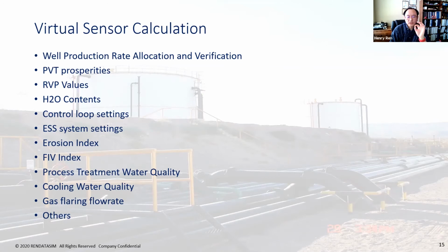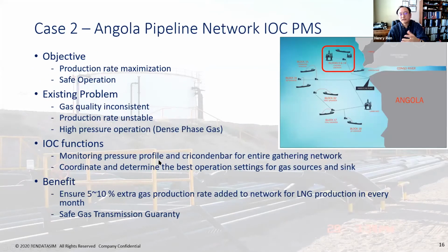And also for the key locations, particularly the downstream of the choke, each riser choke, erosion has to be considered. And for the southern part, there is vibration, especially the seawater dump hole has a lot of vibration, because of design issues, but when it comes to operation, how are you going to manage it. There are so many things being considered. Okay, this is a kind of normal practice they have even today.